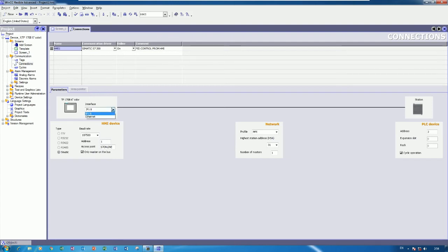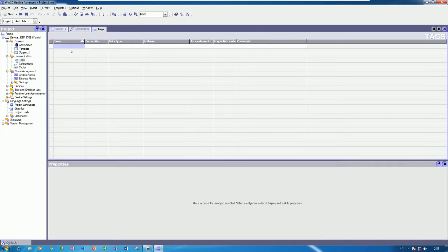And we will use the PPI connection, and then choose the baud rate. Normally I choose 9600 for baud rate, and use the port IF1B, and here is the address of the PLC S7-200 CPU 224 HP. Okay, so let's go to create the text.